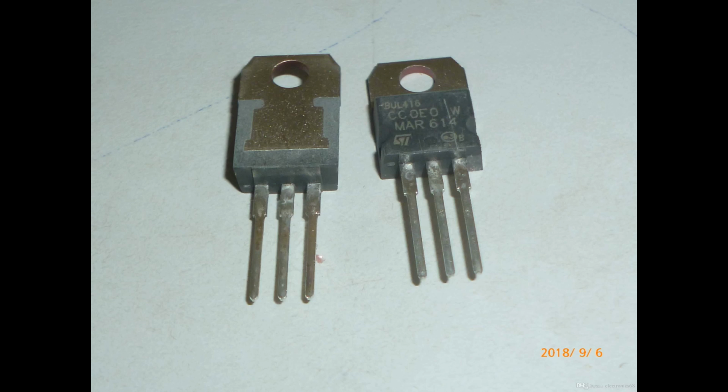Phase modulation, PM, alters the phase of the carrier signal based on the information signal. Voltage-controlled phase shifters, which often use transistors, are used in phase modulation. Transmitter. The phase shifter, controlled by the information signal, introduces phase variations into the carrier signal, resulting in a PM signal. Receiver. In the receiver, transistors are used to demodulate the PM signal and recover the information signal.